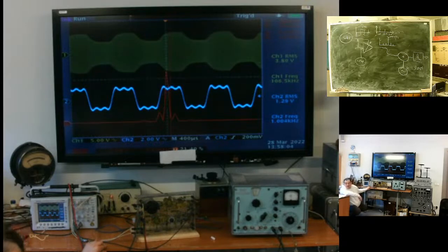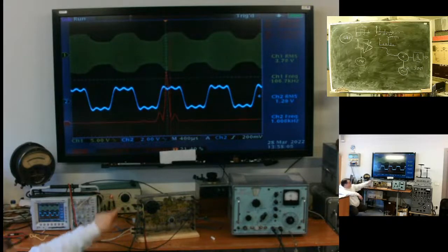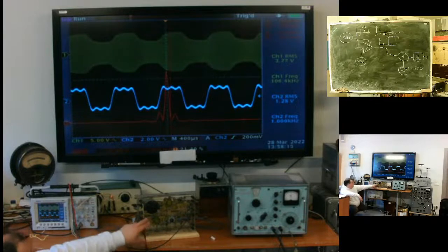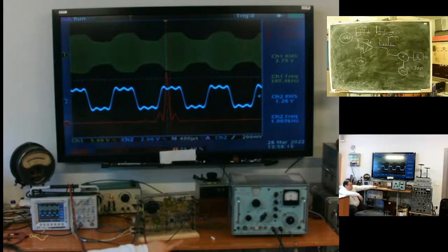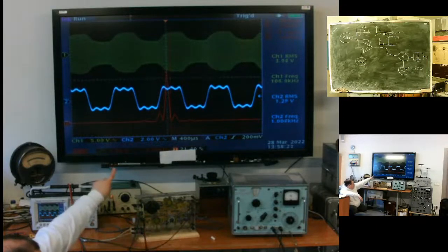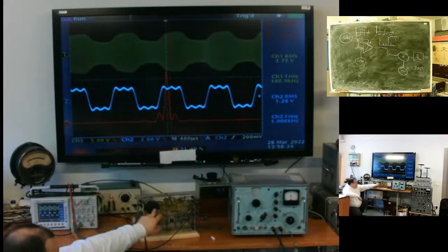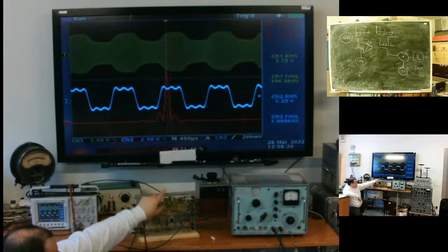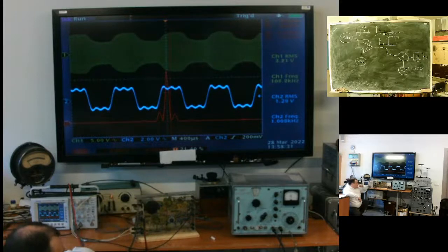I have transferred all the spectrum to 1.7 megahertz from 1 megahertz frequency. Carrier 1 megahertz, it is modulated with 1 kilohertz, and with the heterodyne frequency of 900 kilohertz, it's being transferred to approximately 106 kilohertz frequency.